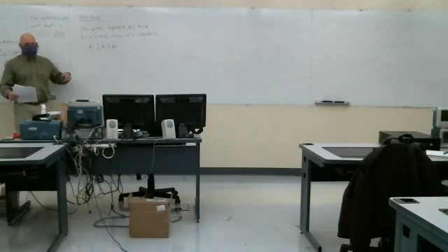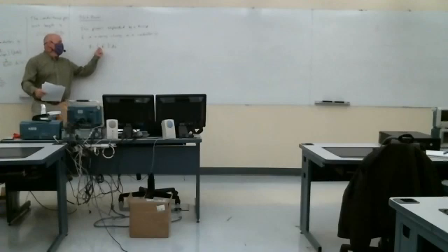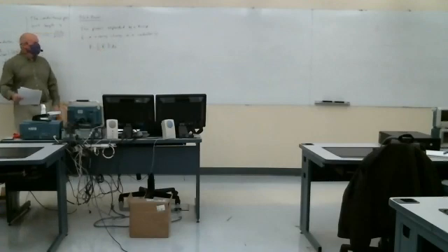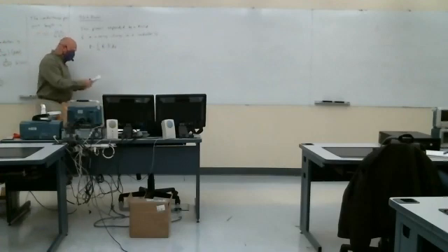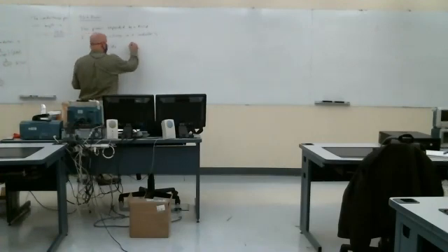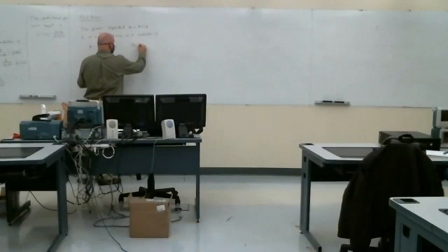The physics, you can look in the textbook, where it goes back to Coulomb's law for the force exerted on a charge due to the electric field, and derives this equation. But from a unit standpoint, it makes sense. The electric field times the current density has units of watts per cubic meter. We integrate over volume, and we get watts. This is called Joule's law.